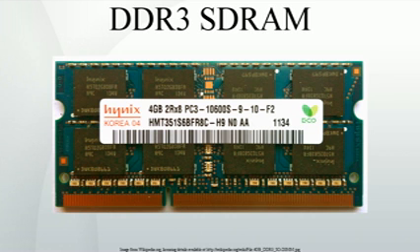Modules can also be fully buffered, which are designated by F or FB and do not have the same notch position as other classes. Fully buffered modules cannot be used with motherboards that are made for registered modules, and the different notch position physically prevents their insertion. Feature summary.